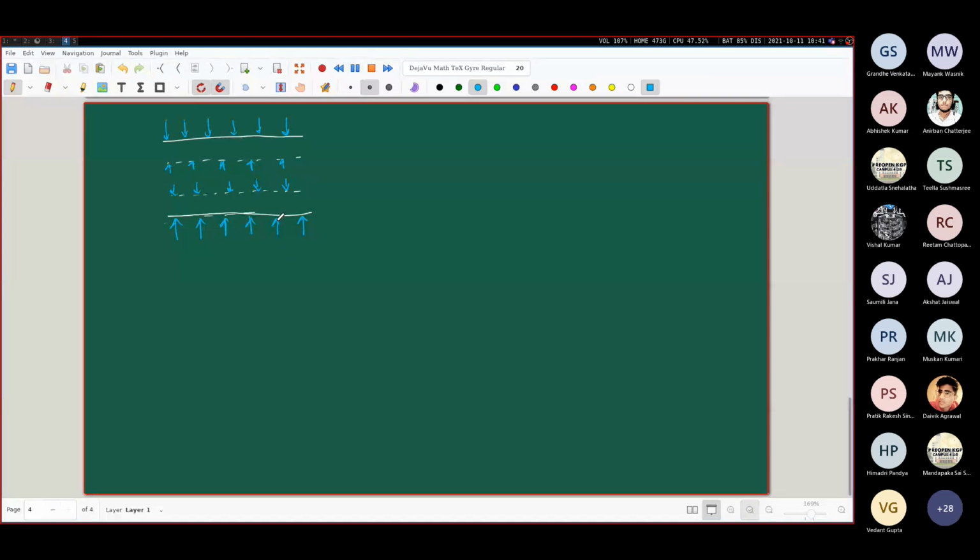Think about it. What are the requirements for plane strain? For plane strain, you must have the loading taking place in such a fashion that there is no distribution of the loading along the z direction, which is very much satisfied here because the pressure is uniform along the z direction. Remember that this is the z direction.